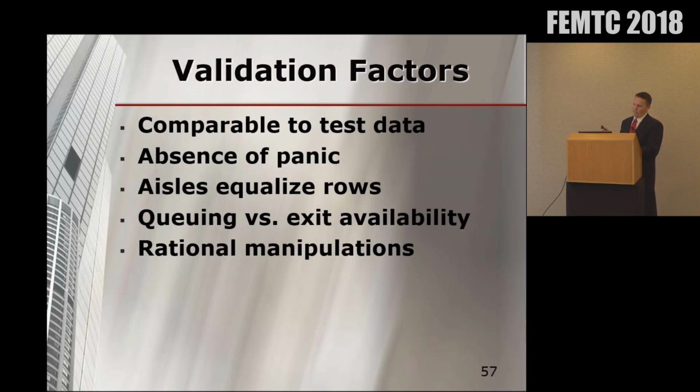So we have to look back and remember that the way that the model was validated was through video footage of lecture halls or other similar arenas. So there's some justification there to rely on the results of the model. We're assuming that there's an absence of panic because there's an orderly exit, and we're able to remain ahead of the developing smoke layer.